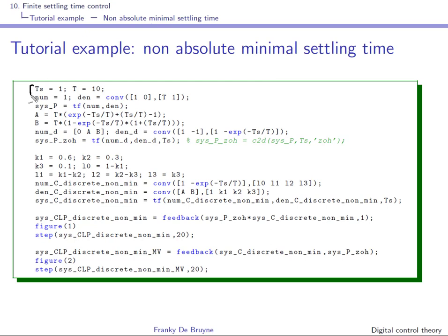Again, this is the zero order hold equivalent description of the system, and here we can play with K1, K2, K3, and then from K4 they're all 0. This means that the error will be, well, 1, so delta K plus K1 delta K minus 1 plus K2 delta K minus 2 plus K3 delta K minus 3.